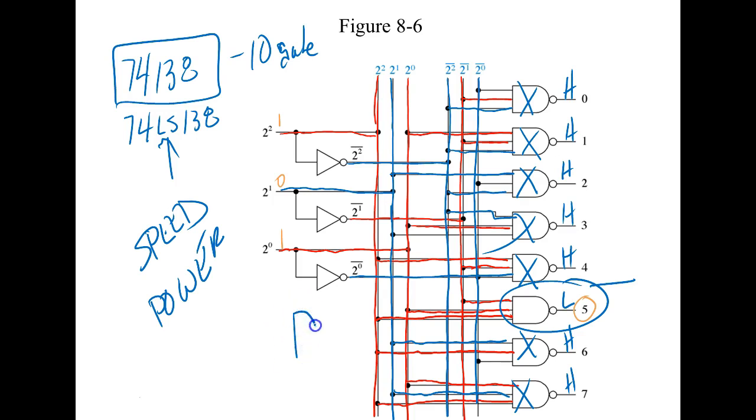So if I came over here and did this, that means this guy right here has 3 inputs. Every one of those inputs pulls a certain amount of current. About 400 microamps for a high and about 1.6 milliamps for a low.